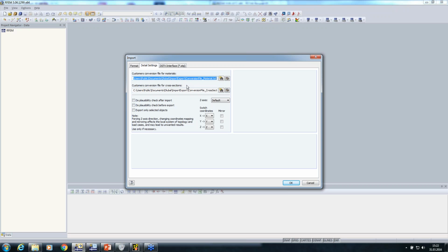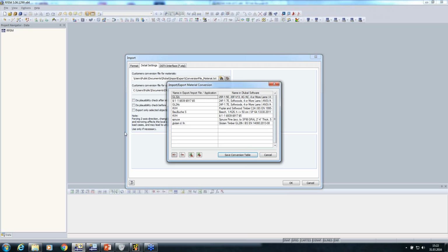Every profile and material has a slightly different name in another software, just because a CAD program must look at other things than we must look at in the static design. So right here I already changed a few things. What we could try out is just delete the glulam that Christian defined for the truss and then see that it's not working and then change it afterwards.